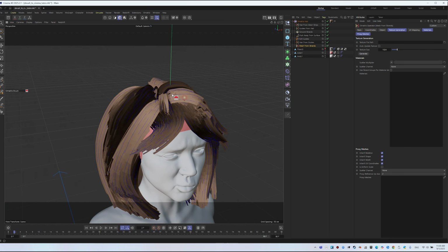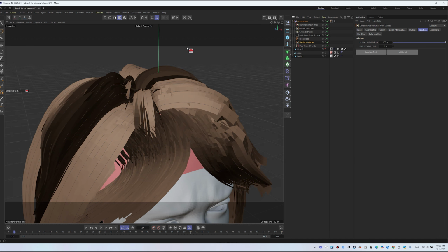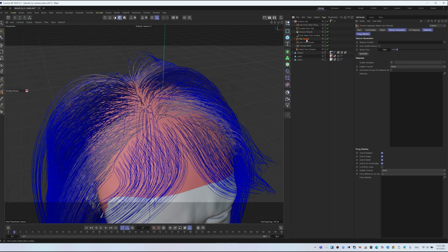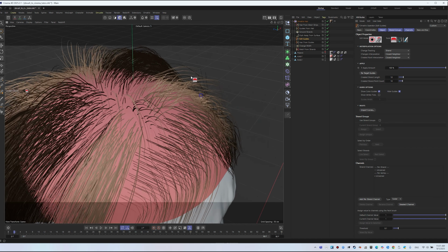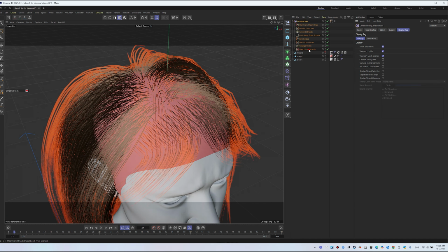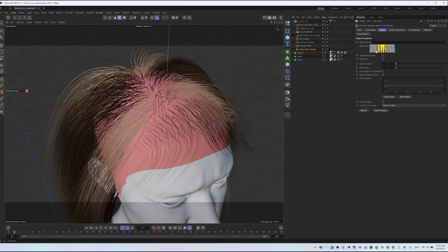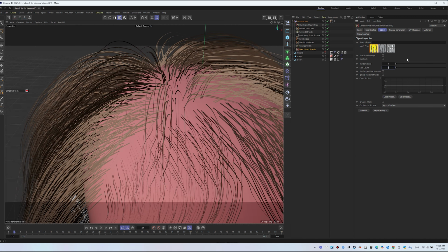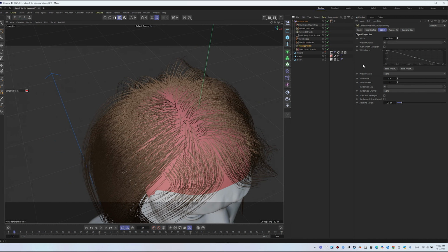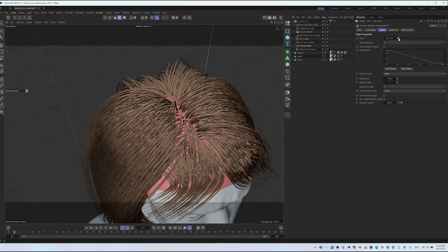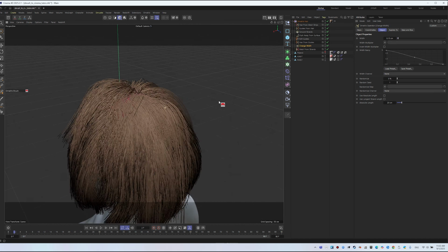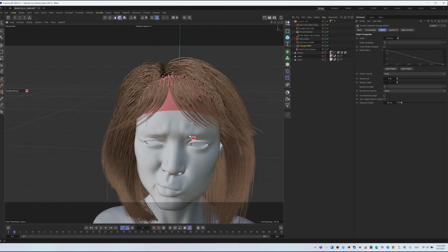You will see the strands as geometry. Reduce the width in the Change Width modifier, so the strands are not too thick. In Edit Guides, turn off guide visibility, so only the mesh strands show during this preview. In MeshFromStrands, choose a cylindrical mesh and set sides to 8. In Change Width, you can experiment with hair radius to better reveal any intersections. With these settings, you will see an identical copy of the hair from ZBrush.